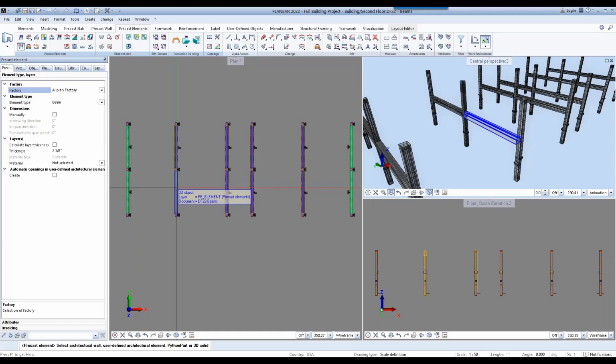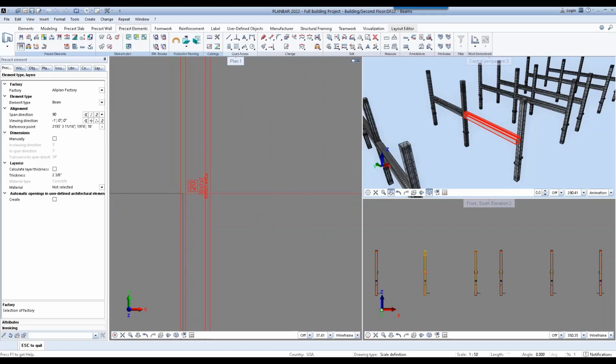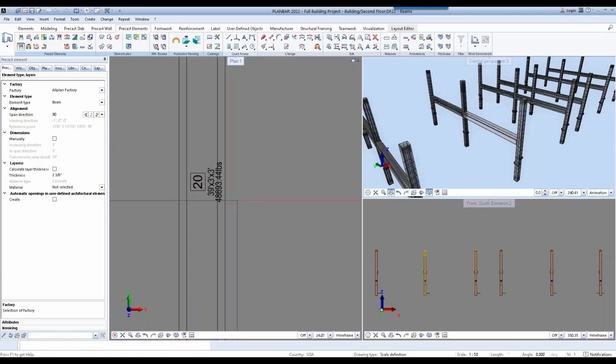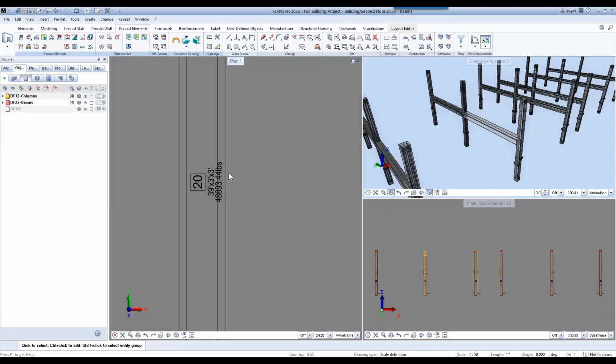So after we've activated our tools and configured our tool settings, all we need to do is select our 3D object. And there we go. Easy as that. It's a precast element. The tool has added a mark number and then also added some additional information to the label. If I hit escape to exit, I can hit it again to escape out of the tool. The label just tells us the piece mark number, the overall length, width, height, and then also the estimated weight.